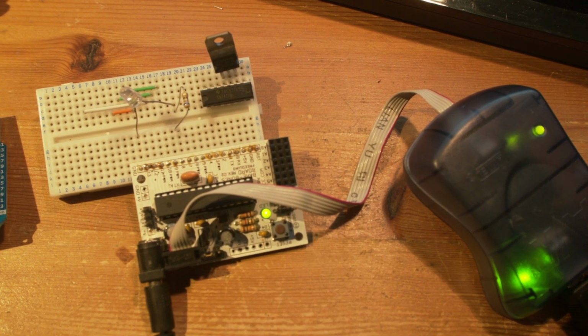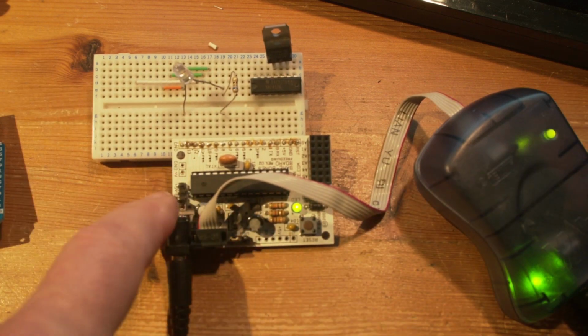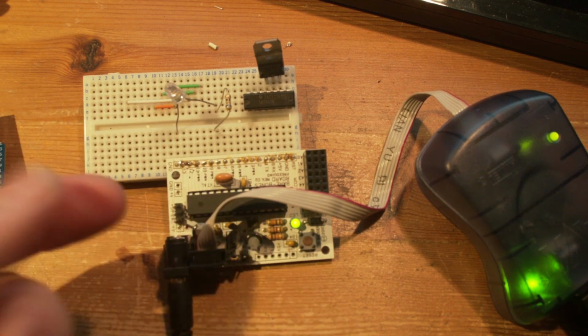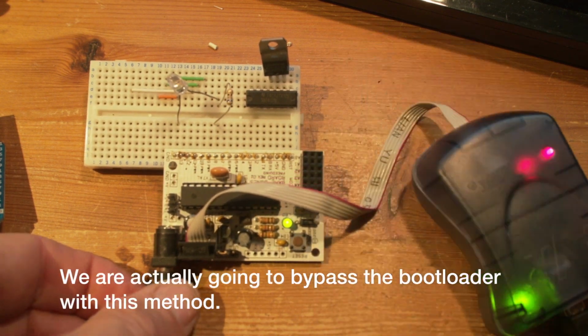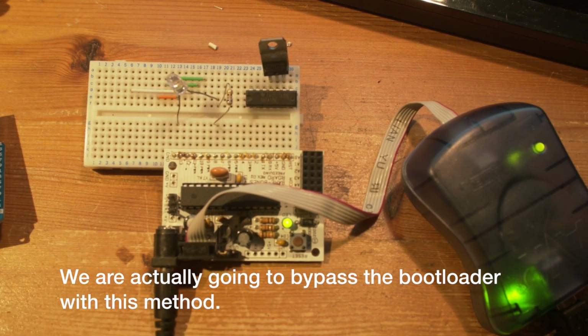Okay, now I'm going to show you how we're going to program this little Arduino thingy. It does not have a USB, as you can see. In fact, you can get an outboard little USB board you can plug in and wire up. But I'm going to do it with this. This is an ISP, an in-circuit programmer, that comes from AVR, and you can buy these online.